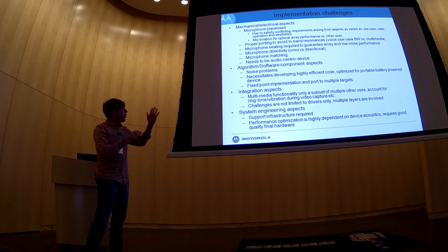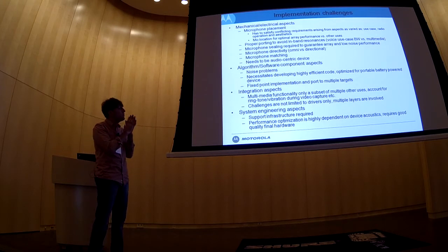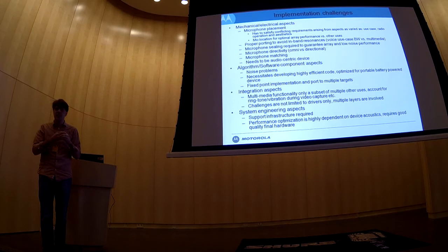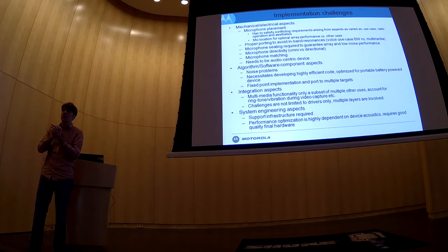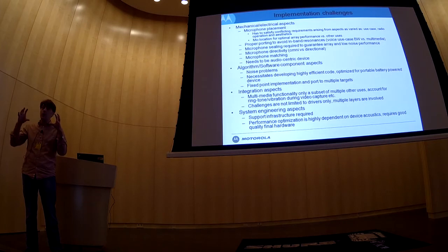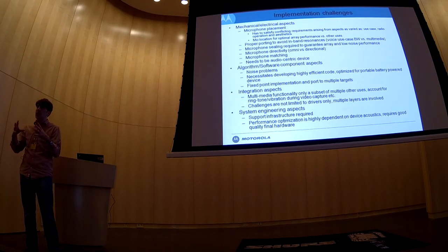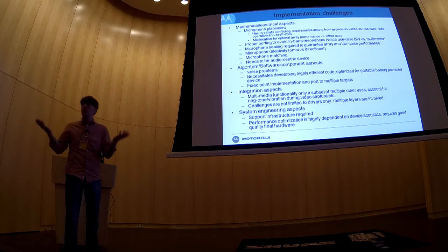That said, what else? Microphones need to be matched in response. We didn't discuss it, but it's a well-known fact that the differential array is particularly susceptible to microphone differences. So that imposes some requirements on the microphone manufacturer, and when you tell them, well, we want these microphones to be plus minus dB, they say, oh, why? No one wants that. That becomes a problem.